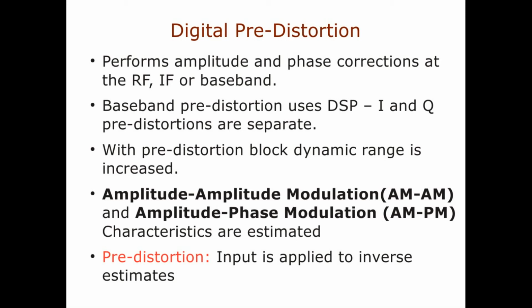So one way to test whether a particular circuit or a transmitter has a phase or a magnitude distortion is by actually passing some predetermined tone of frequency, say f.